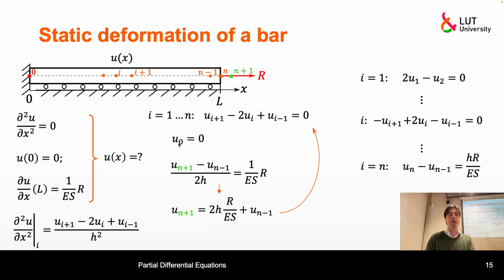But it results, at least as you see even here, we didn't say anything about variational principles, but still there is a very different way how we impose them. We just impose directly our boundary conditions for this left end, essential boundary condition, and we kind of incorporate this second type, this natural boundary condition, into our equations, into our numerical representation of equations. You can see that now we have this set of equations with this applied force substituted into them.